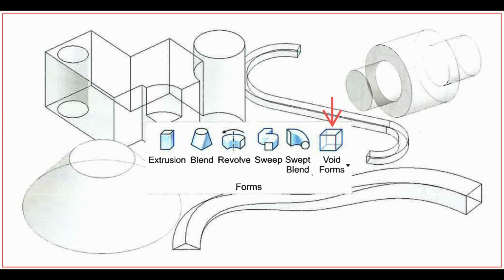Understanding the relationship between solid and void geometry is essential for precise modeling and clean geometry control. Cutting and joining geometry. Finally, we explore how solids and voids interact, how to cut solids with voids, how to join solids together, and how the order of operations affects the outcome. These behaviors form the basis of all 3D detailing and help ensure geometry remains clean, editable, and efficient.